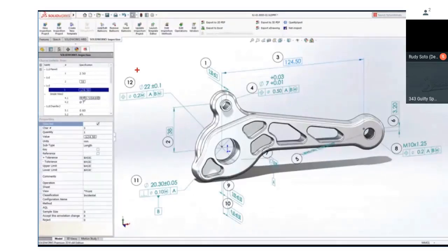And then the user went in with SolidWorks Inspection and created the inspection report on the 3D model. So you can see all the inspection bubbles here. The person doing the inspection would either have SolidWorks and work right inside of SolidWorks Inspection, or they would work from a neutral file format like a 3D PDF that has these bubbles and has the inspection report as a separate document.